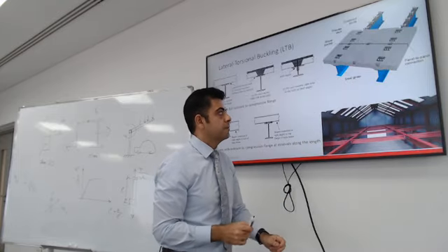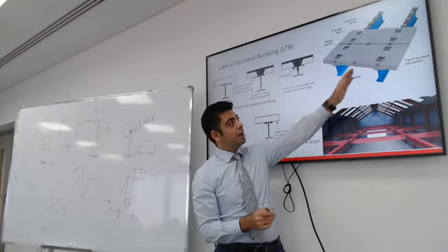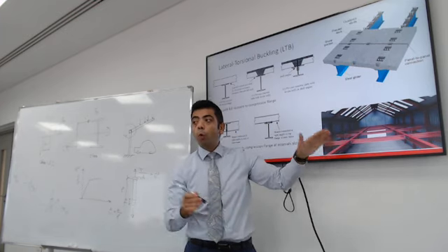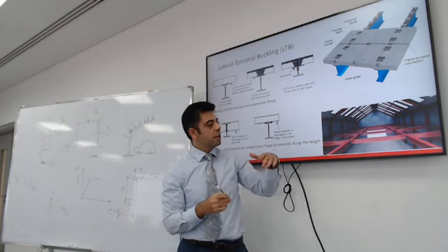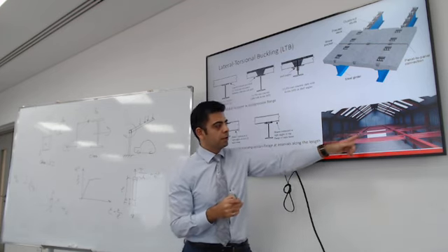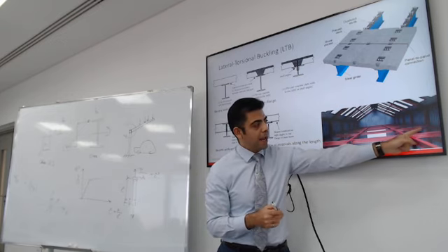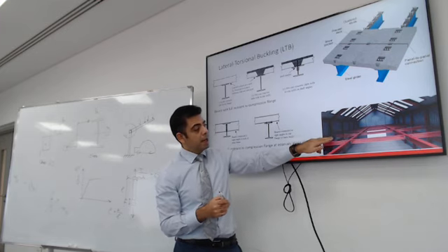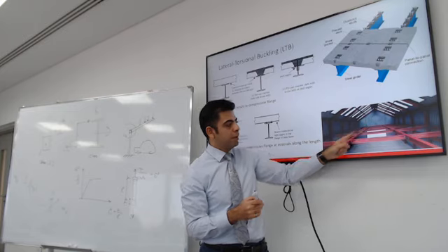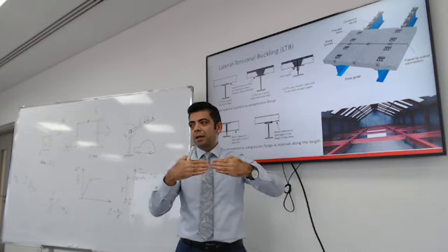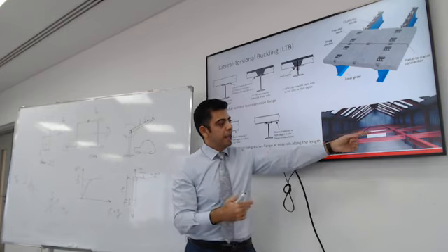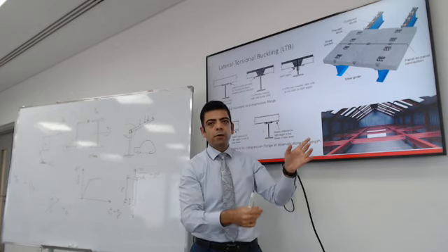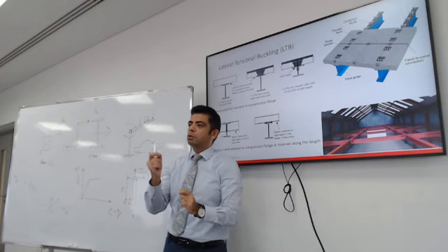So here is the difference. This is a beam that has a concrete slab on top of it. And this is a bunch of steel beams with nothing on top of it. All right? So think of this horizontal beam. At the very end, it's connected to the column. At the opposite end, it's connected to the column. In between, there are only 2 points that are restrained laterally at the cross beams. In between here, if you apply a load in the middle, this beam could buckle sideways. So you need to design this beam for lateral torsion buckling.